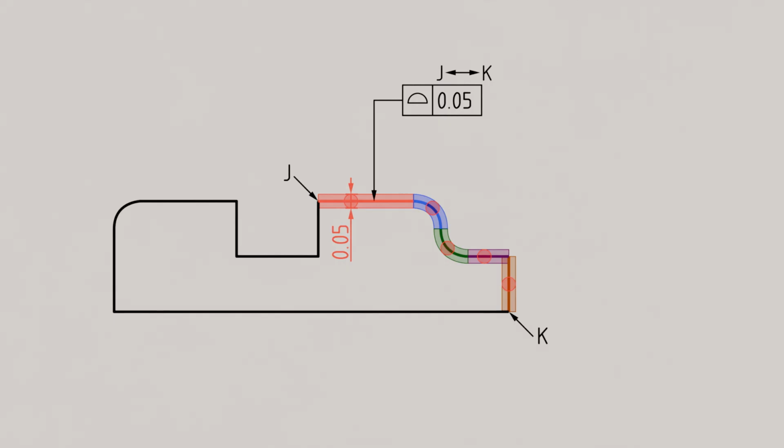The respective tolerance zones are schematically shown in different colors in the drawing and must be inspected independently of each other. However, the individual tolerance zones can also be shaped as shown, with each geometric element still lying within its tolerance zone. Thus, the part is considered acceptable even though the overall shape obviously looks quite different from what we originally expected. Therefore, at this point as well, we must clearly indicate with the CZ modifier placed after the form tolerance value that the tolerance zones of the geometric elements are not to be considered independently, but combined.